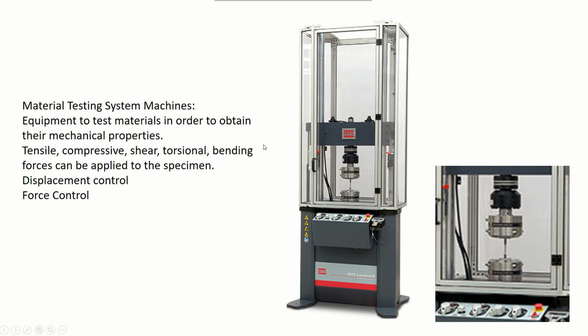displacement control, which basically determines how much you want to move, or how far you want to move, this mobile grip in the vertical axis, or force control, which means how much force you want to apply to the specimen.